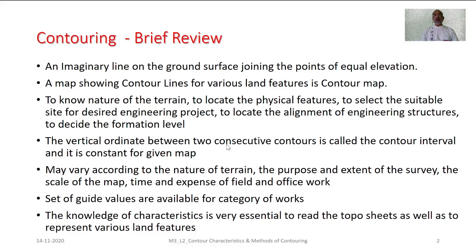The value of this contour interval may vary according to the nature of the terrain, the purpose and extent of the survey, the scale of the map, as well as time and expenses related with field and office work. For certain categories of works, guide values are available, ranging from 0.2 meter to even 25 meter, the way we discussed in our earlier presentation.